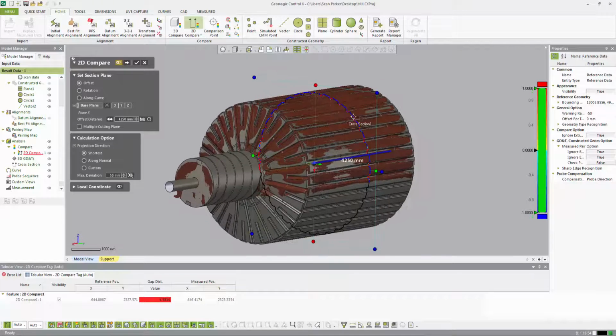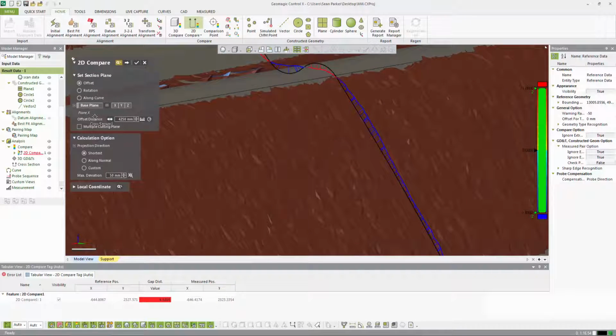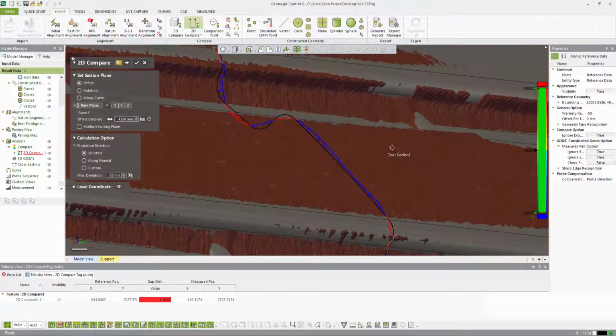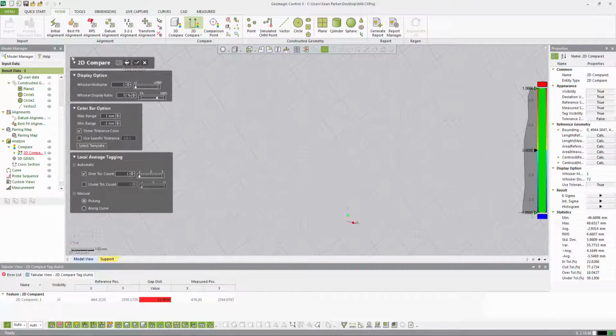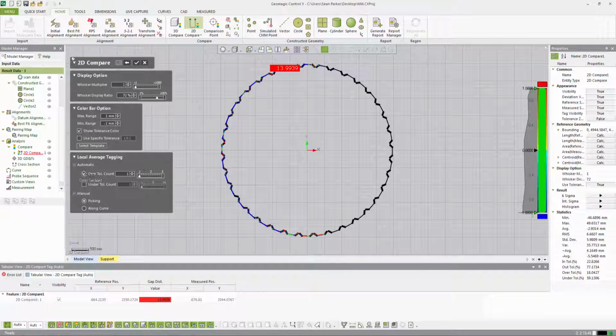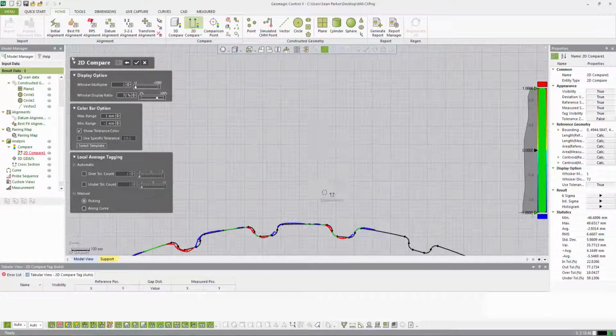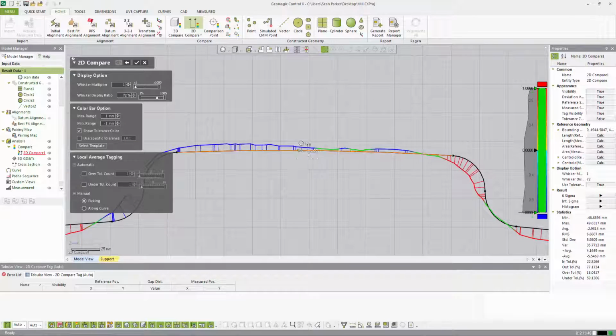I'm going to see a lot more of my deviation. If I change this back to 5 like it's initially giving me, I'm starting to lose areas where I have more than that amount of deviation. So 50 is typically fine. If I expect to see more than 50 millimeters deviation, change it to the maximum, so maybe 100 millimeters or something. And then when I hit next stage, what I want to see is if the deviation right here